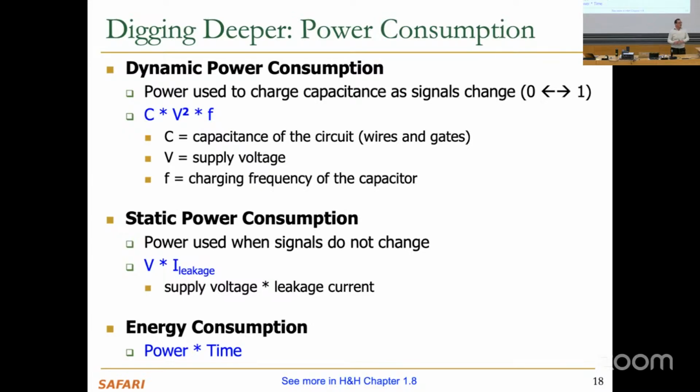If you think about a microprocessor, it consists of many millions of gates, and the program is exercising many of these gates. Every one of them is consuming dynamic power if they're switching. Also, every one of them is consuming static power at the same time when they're not switching. The total energy consumption you get is the combination of those powers over time. Does that make sense? Okay.